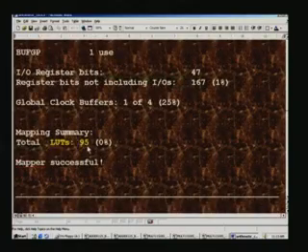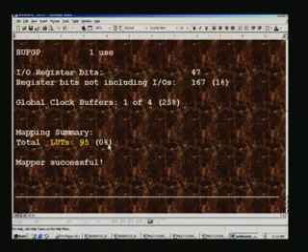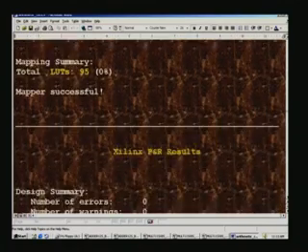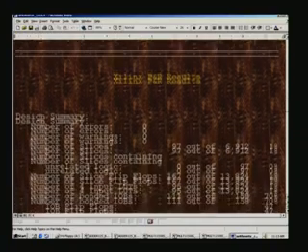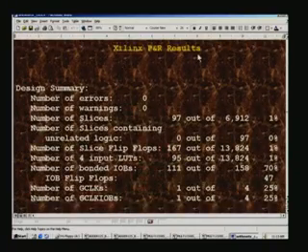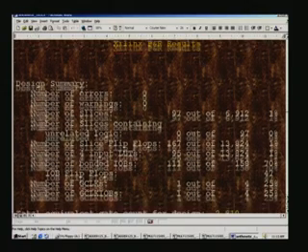It takes only 95, although it says 0%, it can't really be 0 there, it is a fraction less than 1%. So that is the simplify result, and here come the Xilinx place and route results, and you have all the slices, flip-flops, LUTs listed here.